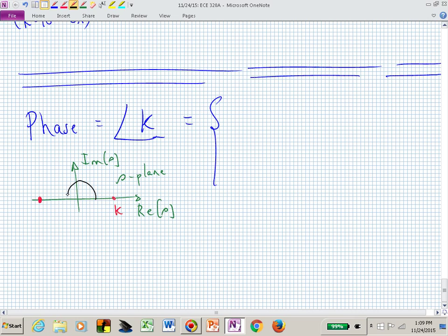But if it was negative, then I actually have to turn 180 degrees. And typically, since we think of things happening later in the output than at the input, we usually get to that same point by going a minus 180. They're equal, but I like to just say if it's negative, let's just assign it an angle of minus 180 degrees. If it's positive, it's 0. And it's that value for all frequencies.